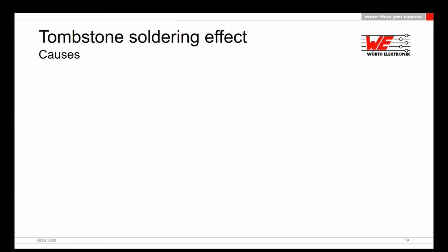The most common issue while working with the side view LEDs is the tombstone effect by soldering. The tombstone effect happens when the component flips up during the reflow process. It usually happens with the small SMT components. There are many causes which lead the component to this effect. Just the main cause is only one: the temperature difference on the two sides of the component. And it happens through these issues.